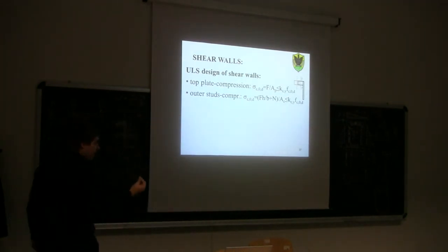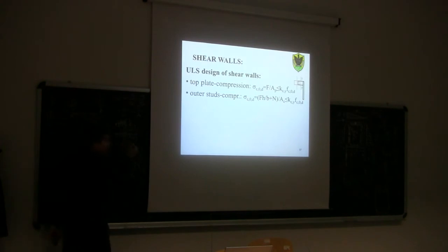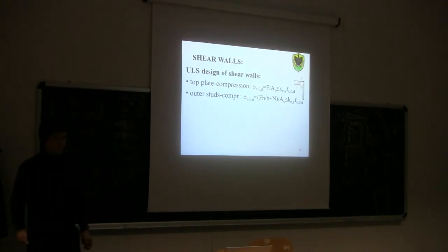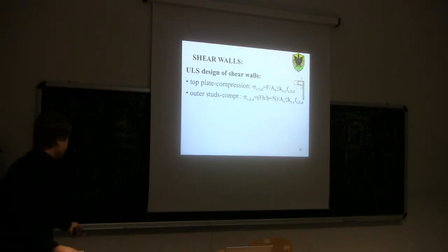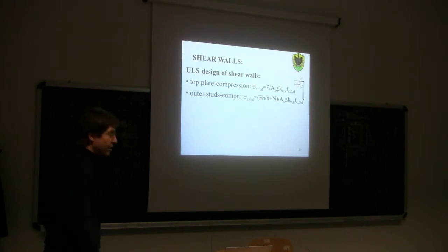However, you must remember that this is an approximation, because in reality we don't have continuity here. In reality there is a discontinuity, and there is one nail connection. So strictly speaking, we cannot apply the same relationship as in mechanics of structures, because here we have a flexible connection, not a glue connection.